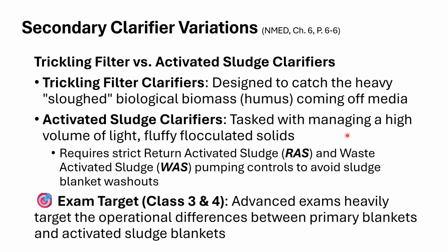Okay, we're taking that as we pump the sludge blanket from the bottom of that secondary clarifier. That RAS portion of it is returned to the inlet of that secondary clarifier. And the waste activated sludge, well, that's just going off for the digester or dewatering, as we talked about in the last chapter or last module.